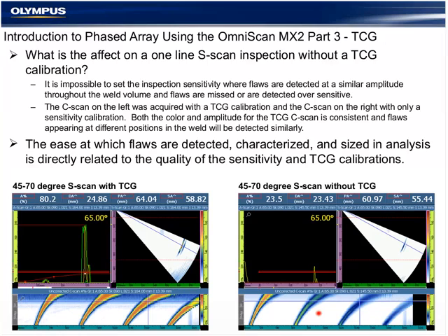And as we can see, as the hole gets deeper or as the angle gets higher, it's a very small indication because it hasn't been corrected. So it's very difficult to do a long sound path good inspection without the use of the TCG. And that's specifically why they are required by most of the codes for new weld inspection that we work to.